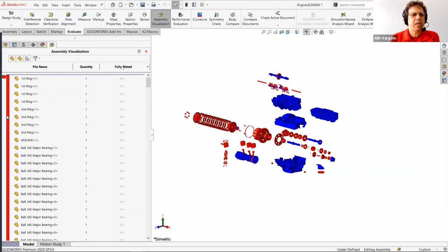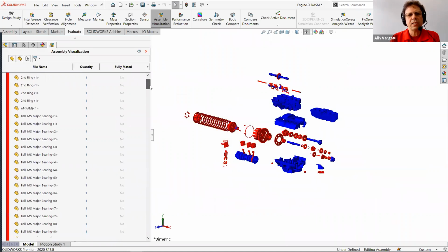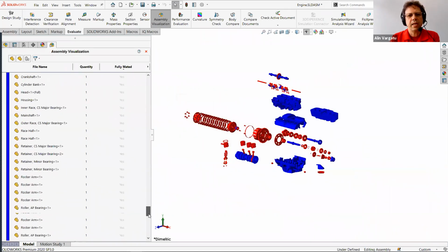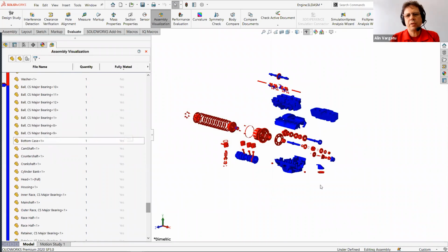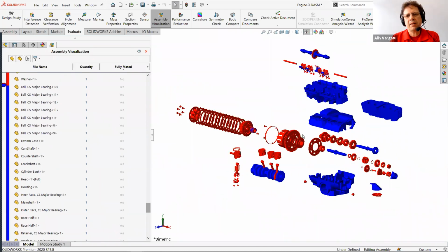No and yes, and let me just ask SolidWorks to reset the colors and again group identical, and I can see the red ones are not fixed, and the blue ones are actually fully defined. This is at the part level. This probably doesn't tell you too much unless you are one of the checkers, because these are in all kinds of different sub-assemblies. And it maybe makes sense for this to be able to move, right? You want to simulate rotation or simulate the movement inside the assembly.